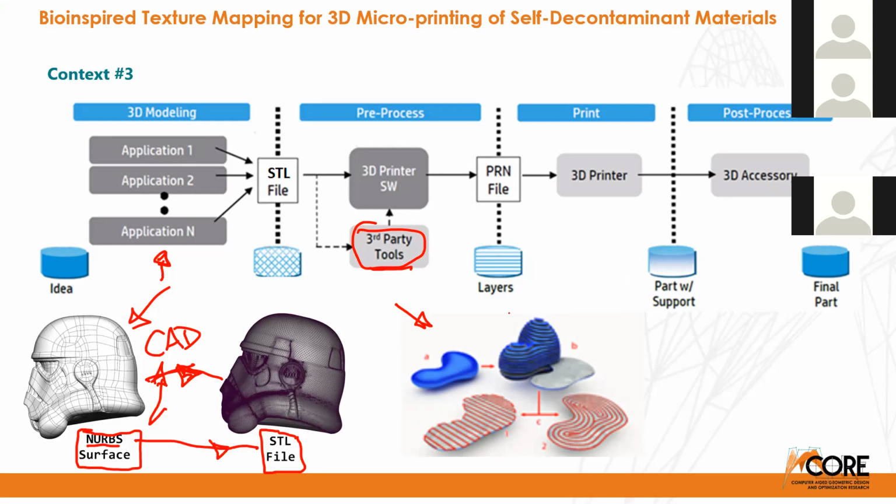So basically, the key point in the 3D printing pipeline is this slicing of the object. Then after the slicing, the object is 3D printed, and after that we have the post-processing of the object, because you may have to do some cleaning or remove some support material that is still attached to the object. And then this is the whole pipeline.